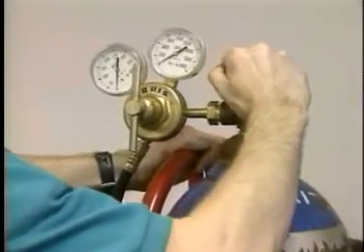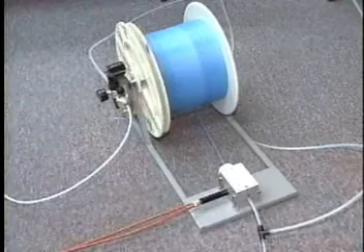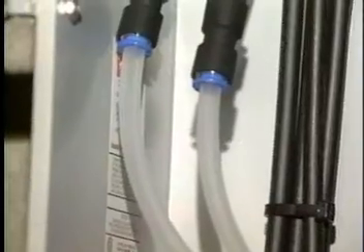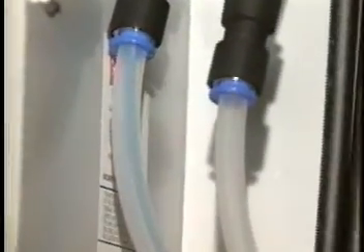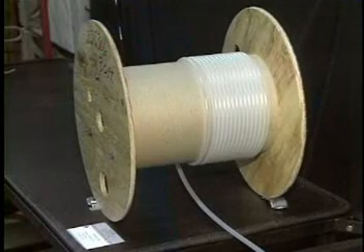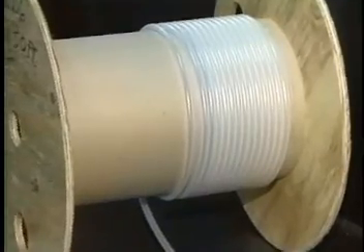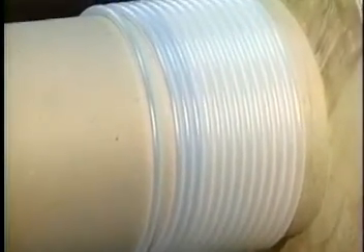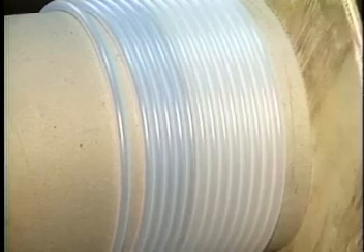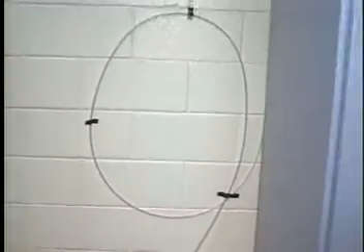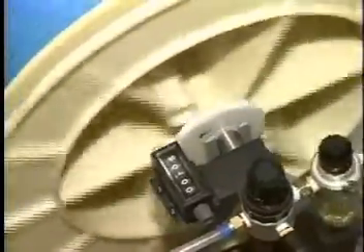When all the junctions have been made, compressed air carries a bundle of fibers through the tube cable past each junction to its final destination. Air pressure pushes the fiber bundle through the tubing, while a jet of air is passed through the tube ahead of the bundle to allow it to float on a cushion of air, eliminating the friction present in conventional pulling. Because there is no external pulling tension applied to the fibers, installation stresses are reduced to near zero. Fiber lengths of up to 2 kilometers can be installed using this technique.